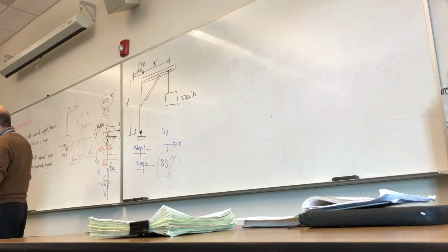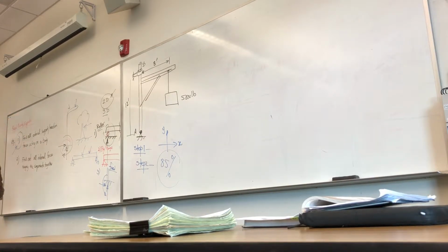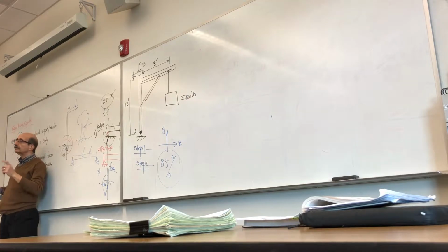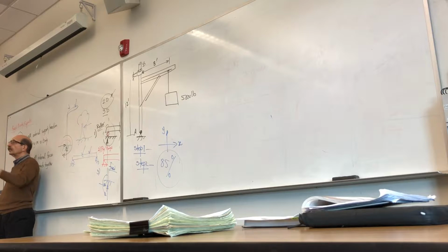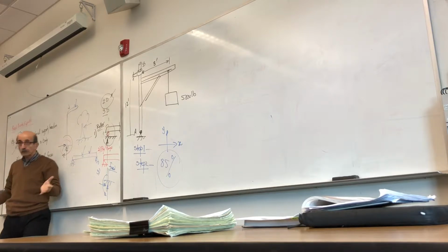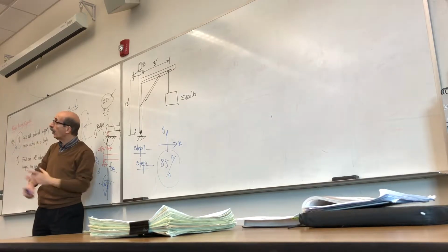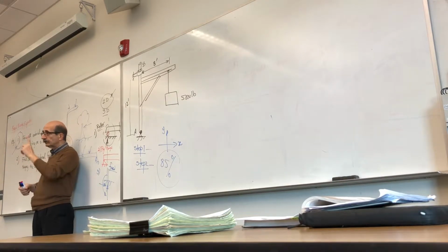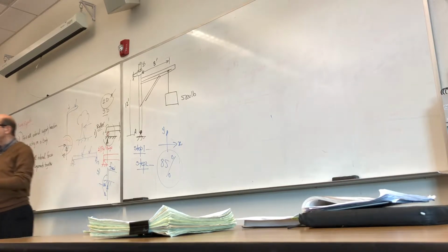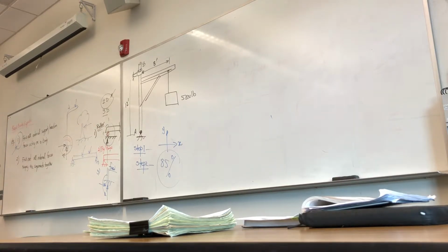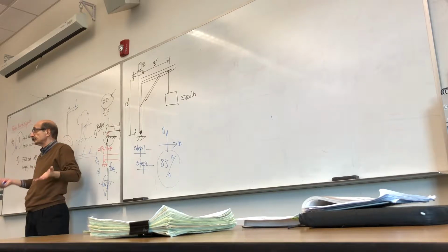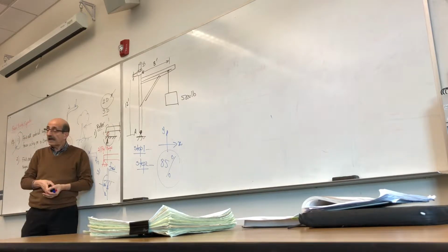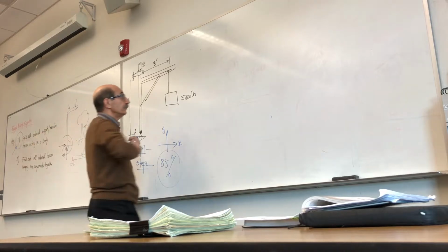We learned that no matter how many forces or moments are acting on a system, they are equivalent to a single force and a single moment. Whether these forces are known or unknown doesn't matter. All forces acting on a structure can be reduced to a single moment and a single force. And when the structure is in equilibrium, that means those sums have to be 0, otherwise the structure moves, right? That's the meaning of equilibrium.